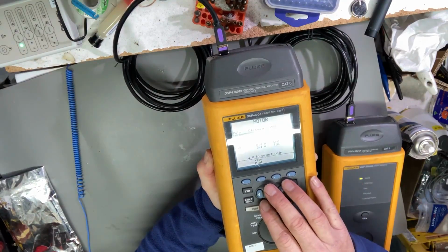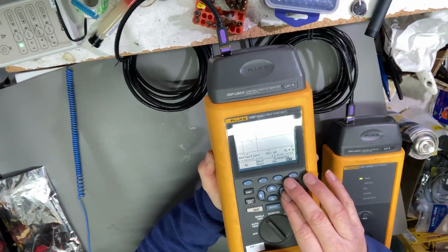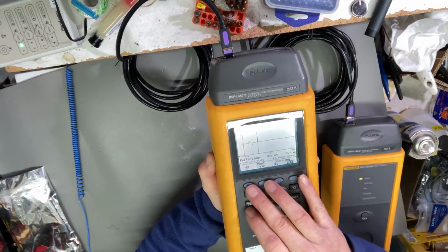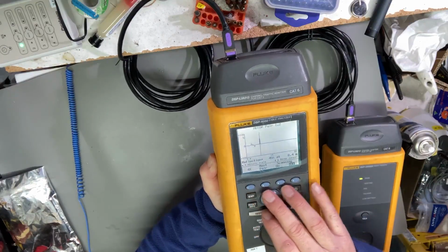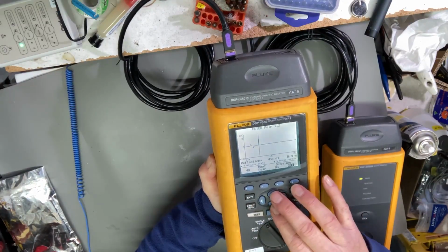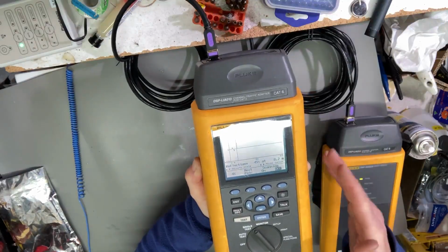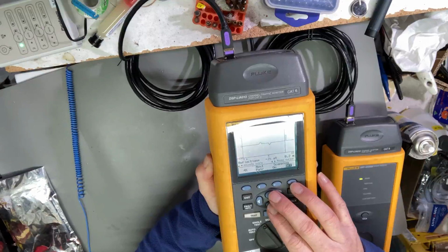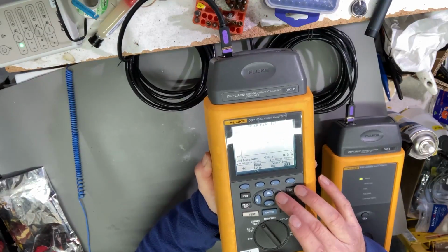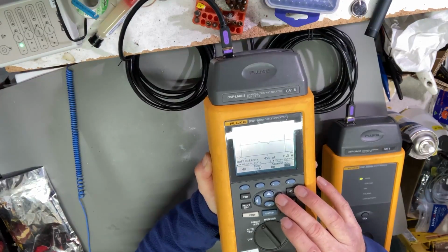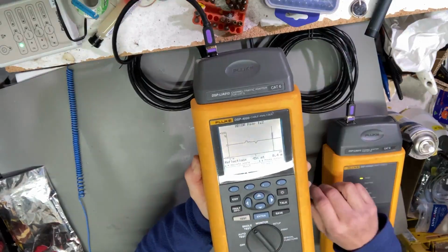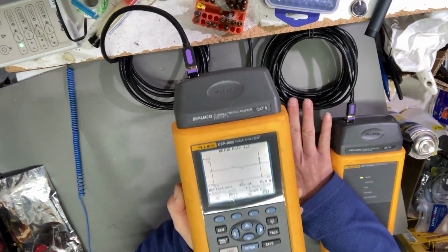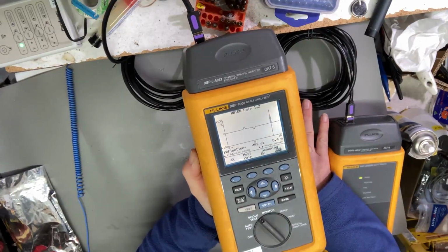So pretty quick to do a single test. Right, now the differential result there. Let's zoom in, I think. So we know it's through 8 meters. So we're going to zoom in. Right, so it's saying 8.4 meters. Now I could calibrate that until it's exactly 8, and that would give us some more accurate distances.